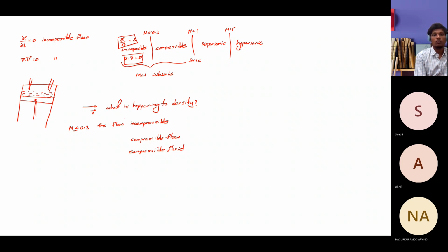Okay. So you should be careful about what they are asking, whether they are saying compressible flow or compressible fluid. Compressible flow in the sense that you have to relate it with the velocity, and compressible fluid in the sense that you have to check what kind of fluid they are talking about. Okay, so that's just one caution I want to mention to you.